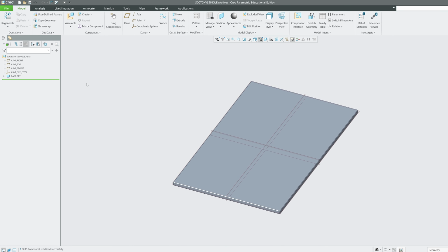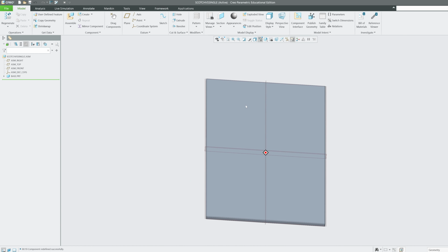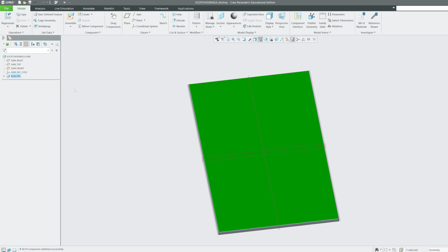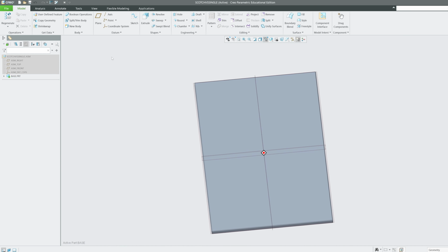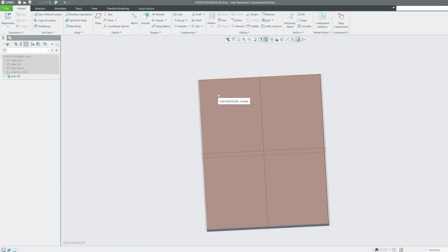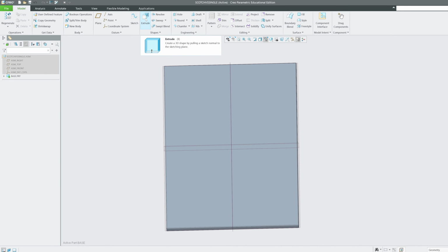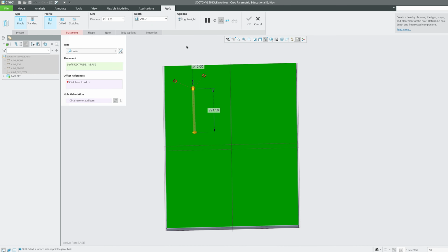Yeah, probably. Now what I'm gonna do next is make some pin joints, and for that I'm gonna create a hole here. Again, I need to activate this part. By activating this part, you do not need to explicitly open the part. In this way you can actually enter inside. And now, yeah, let's add two holes.